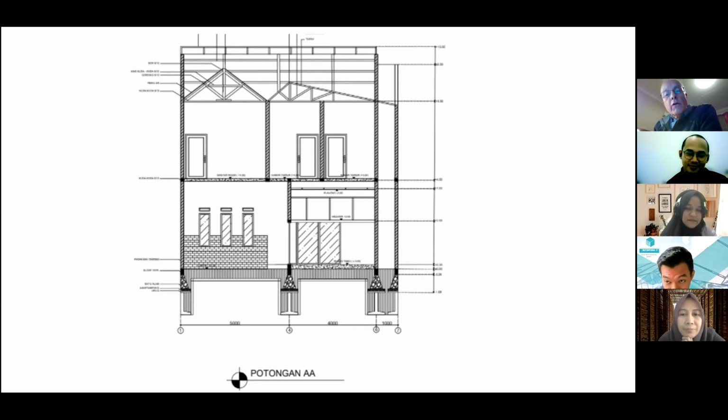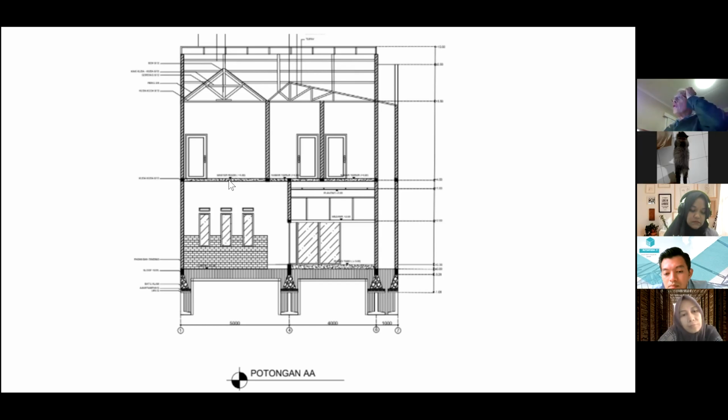And I think this is something I'm a bit worried about, because you are asking the student to do so much work that it's really difficult for the student to do a good careful job, because the student is expected to do so much. And so here's an example where this section is wrong because it doesn't show the stairs going up to the second floor. It doesn't show the opening in the floor. And actually, there are other stairs here, I think it should show, but it doesn't.